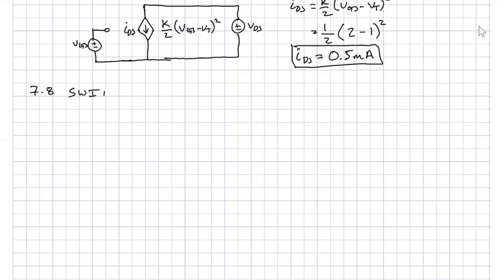We're going to call this the switch unified MOSFET model. All right. So in saturation, this model is not going to change. It's going to still model the MOSFET as an ideal current source.